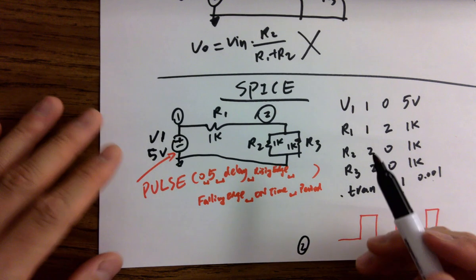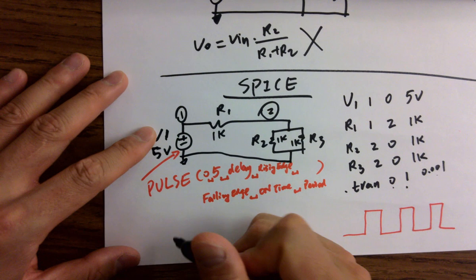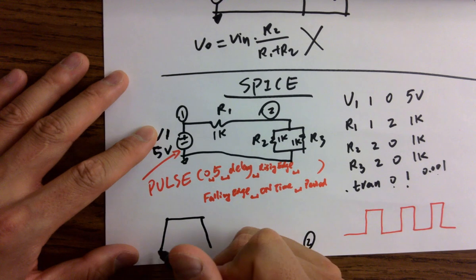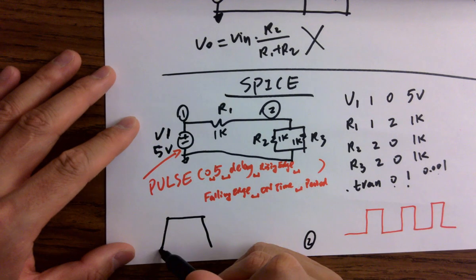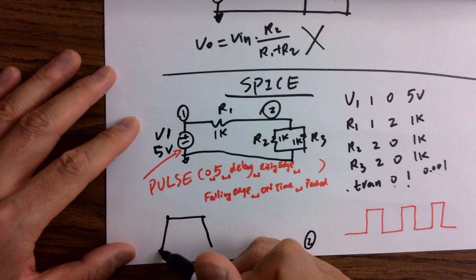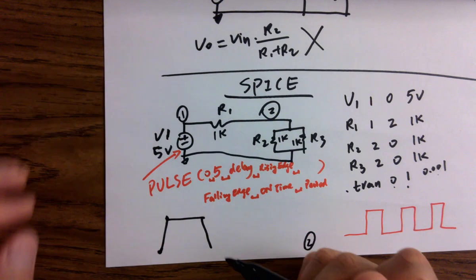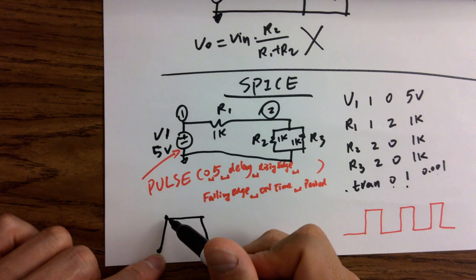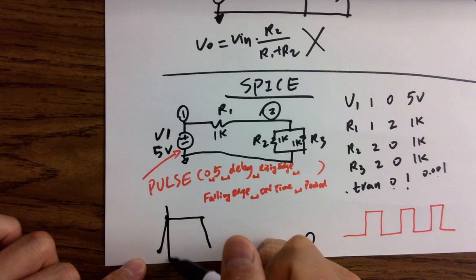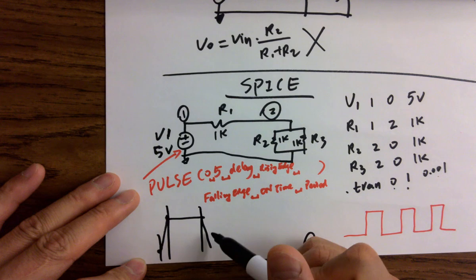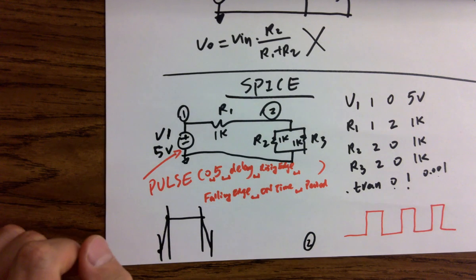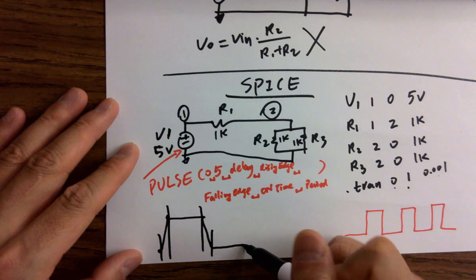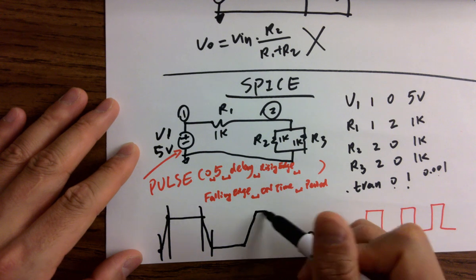So rising edge, falling edge, as a digital signal, if you zoom in, right? The point here and point here won't be instantaneous. There will be a time. It's impossible to have 2 points at the same time point. So there will be a time no matter how fast that is. So this will be the rising time, right? This is the falling time, or the falling edge. And you will have a low and then it goes to high.